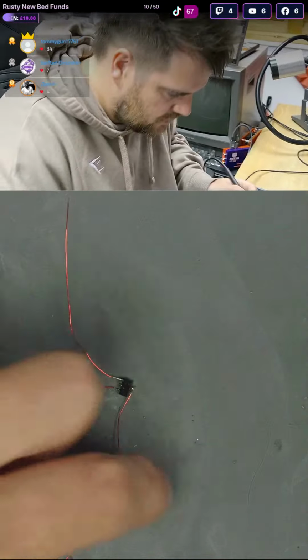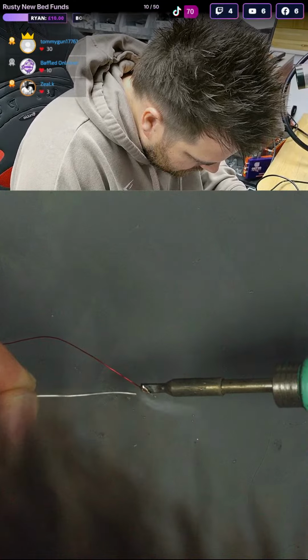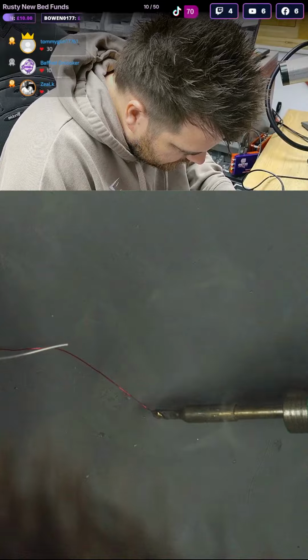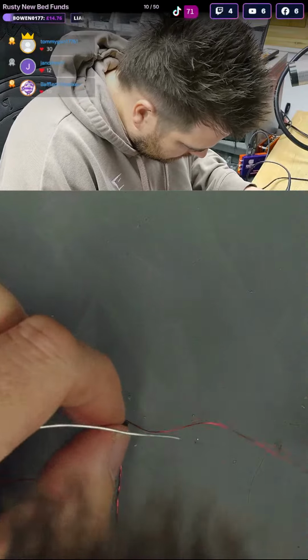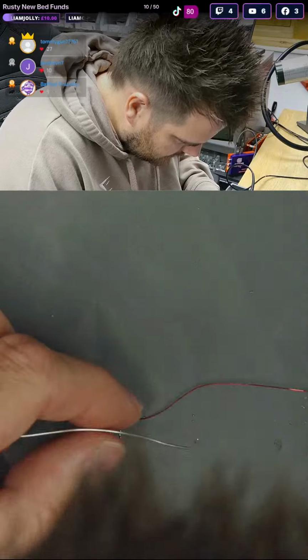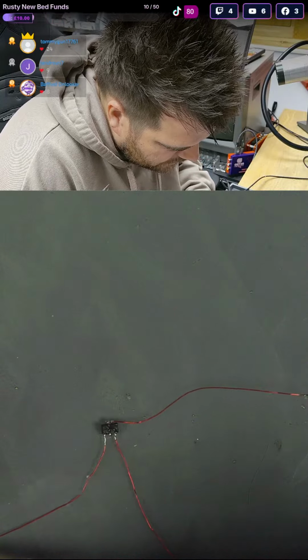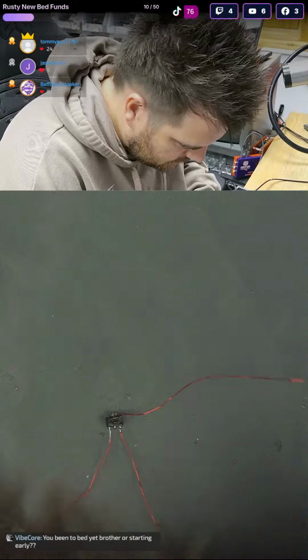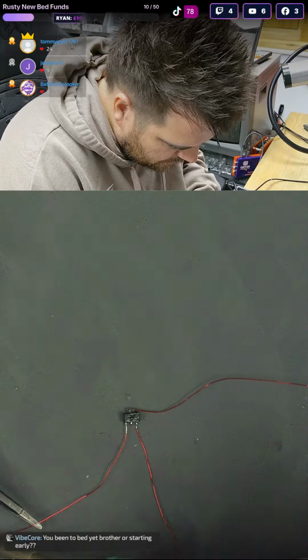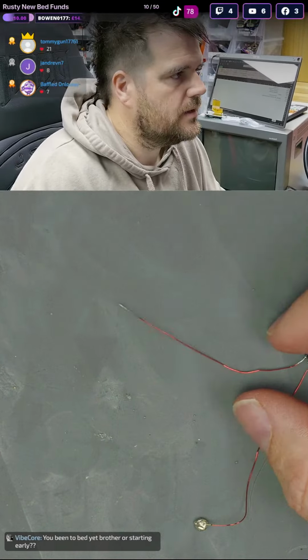Right, and then when we strip these ends, I will fold them over and make a bit of a ball so that we can actually grab onto them with the component tester, or just try and get extra solder to stick to the pins is the goal. But I'll normally make a little loop in the wire and then fill it with solder to make a little tab. That's how you make these thin wires thicker. So we've got this thin wire.